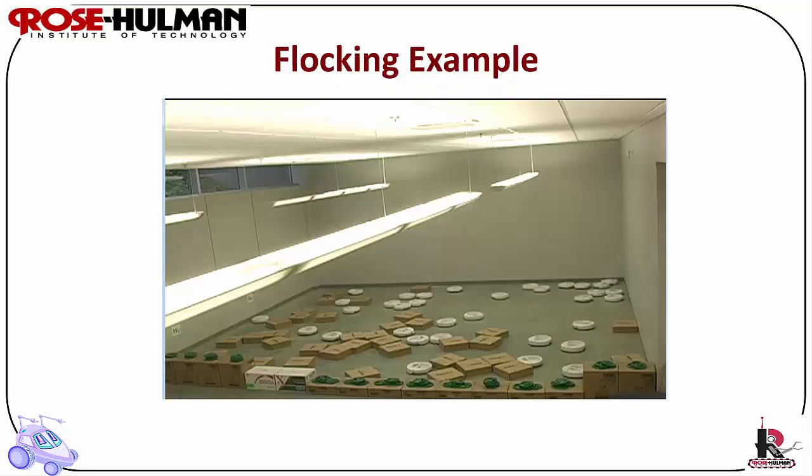To make robots flock together when they cannot communicate with each other, you give them their own roles and own local sensory data and use emergent behavior. This can be achieved with the following rules. Don't get too close to other robots or obstacles, but don't get too far away from other robots or obstacles, and keep moving as long as you can. To get the robots to move to a certain destination, use another rule which moves each robot towards some goal point.